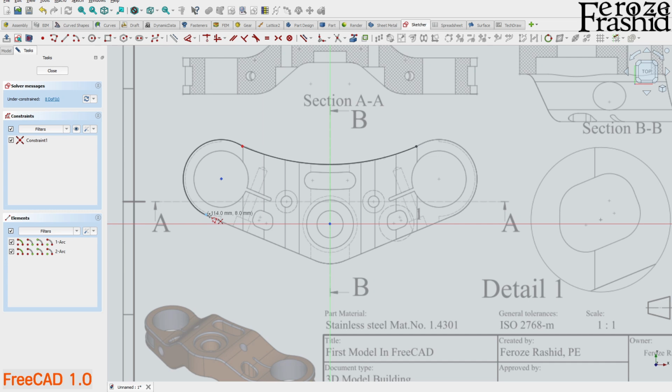So polyline is a little bit quirky. So now, because we are starting from the end of an arc, polyline by default is going tangential to that arc. So we come all the way from here, there, and then there is an arc in the way. So without clicking anywhere, take the mouse to the end of that arc that we want to draw, and then hit M, M, M, one more time.